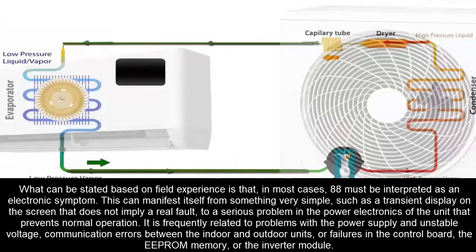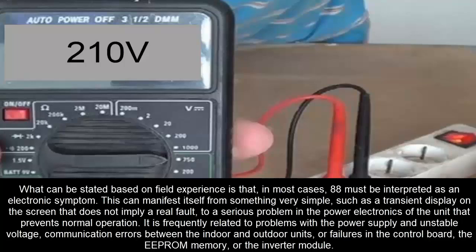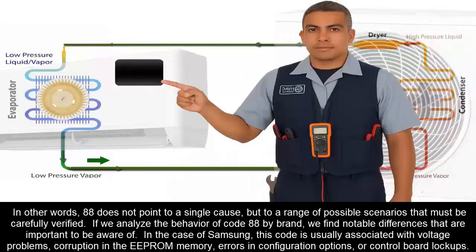What can be stated based on field experience is that, in most cases, 88 must be interpreted as an electronic symptom. This can manifest itself from something very simple, such as a transient display on the screen that does not imply a real fault, to a serious problem in the power electronics of the unit that prevents normal operation. It is frequently related to problems with the power supply and unstable voltage, communication errors between the indoor and outdoor units, or failures in the control board, the EEPROM memory, or the inverter module. In other words, 88 does not point to a single cause, but to a range of possible scenarios that must